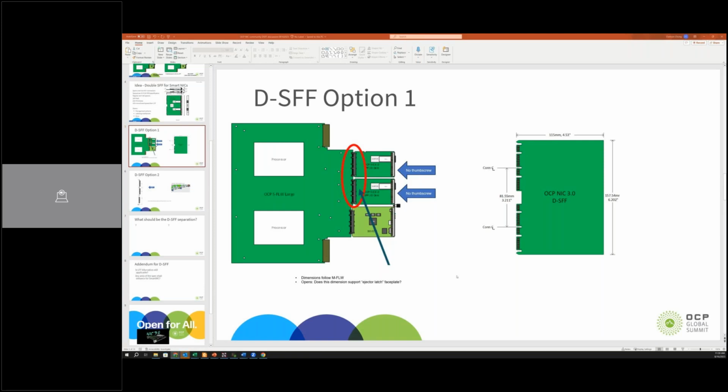When I try to compress everything I want to fit into an IPU card, including timing features like synchronous Ethernet and DPLLs, all the DDR I want to fit, and the largest modules, whether that be dual QSFP or even OSFP, like we've been talking about, I can't even fit that in LFF. And I think this DSFF does open that further, getting more of those features in a card compared to LFF. Okay, since your case is a bit different from NVIDIA, where large enough is good enough.